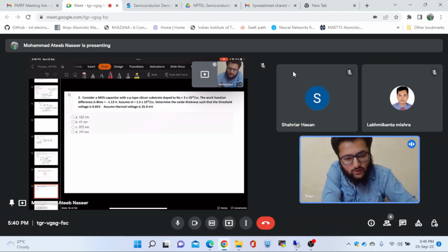So if it's 0, the next DC pulse that we give to the gate will be 0.05, and then it will be 0.1. We will proceed like that. But if it's a fast DC sweep, we might go from 0 to 1 volt directly, and then 1 to 2 volts. That's what we mean by that.